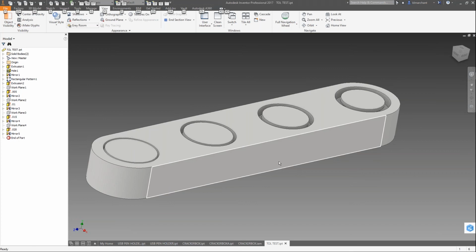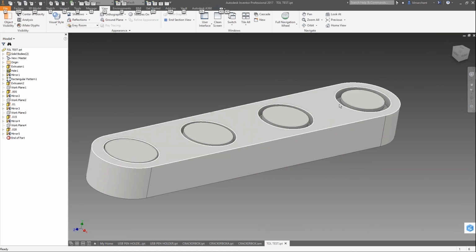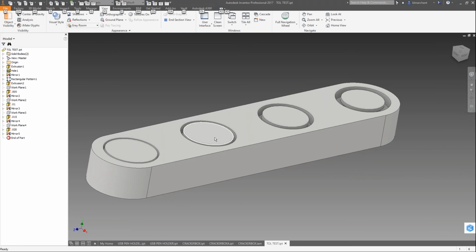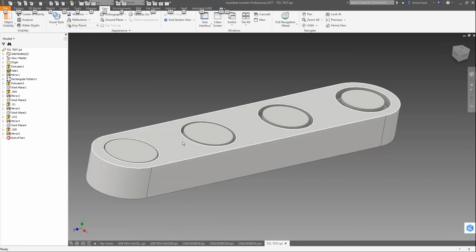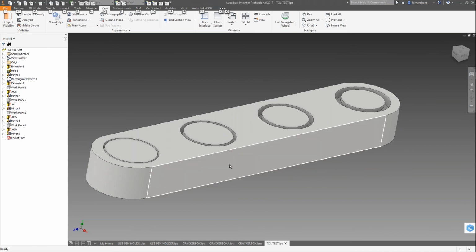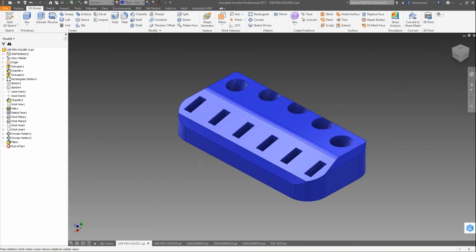So sometimes we may want to create just a part that we can print so we have a reference to go back to. This part would not function well for FDM or FFF technology, just due to the fact that it would be hard to remove the support structure in there. Depending on the diameter of our bead or filament combination, we may or may not see some of that detail.